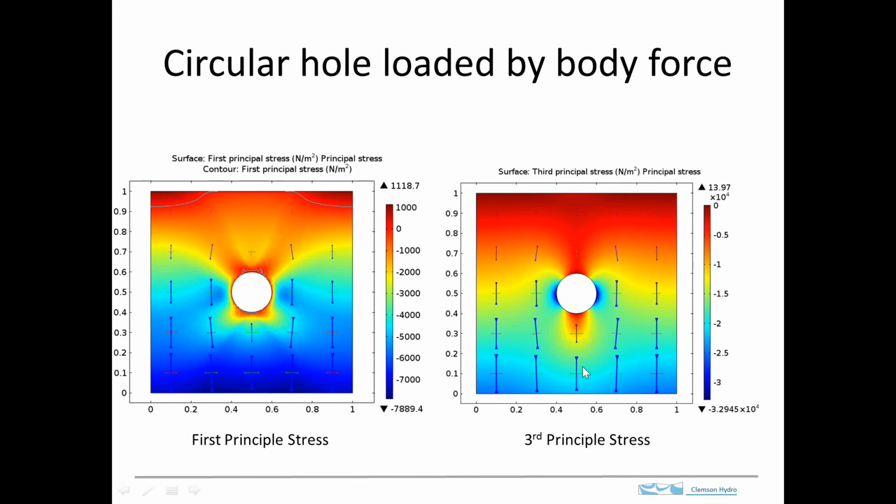So the body force is causing the compressive stress to increase downward, but the stress is being concentrated right here at the walls. It's really the same kind of argument that we had for stress concentration previously, that the lines of force have to go around this region and they get concentrated here in the walls, so we've got large compression right here in the walls.